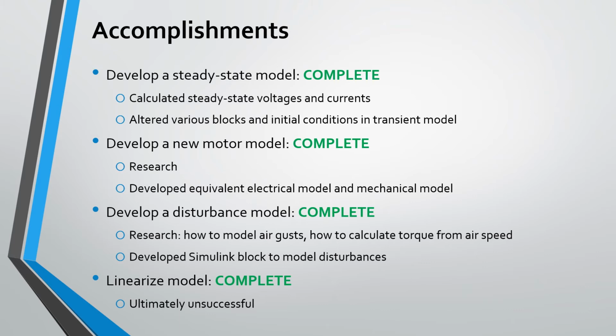The next few slides summarize my accomplishments. First, I developed a steady-state model by altering John Maroli's transient model. This involved calculating steady-state voltages and currents, and then updating various blocks and initial conditions in the Simulink model. Next, I developed a new motor model. The old motor model used a generic motor block, but we wanted to create a custom block that more accurately represents the behavior of the NASA motor. I read a journal article, and based on the article, developed an equivalent electrical model and mechanical model.